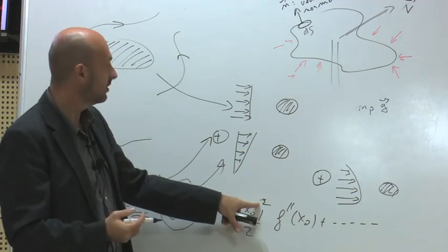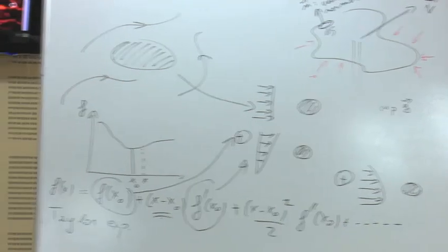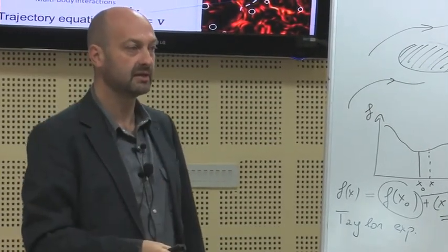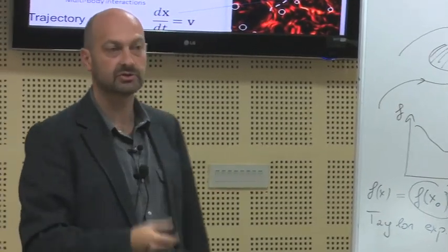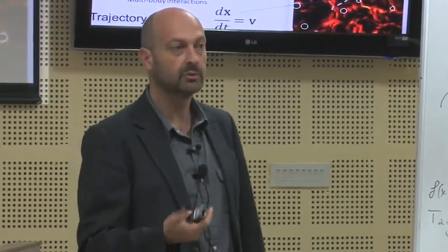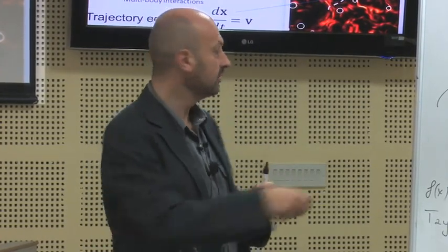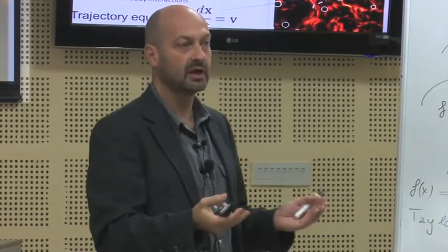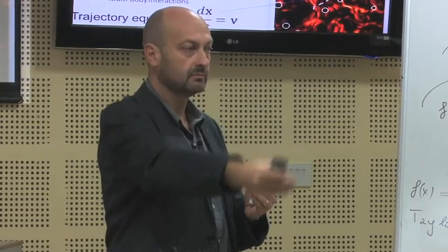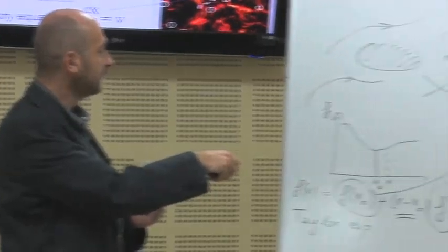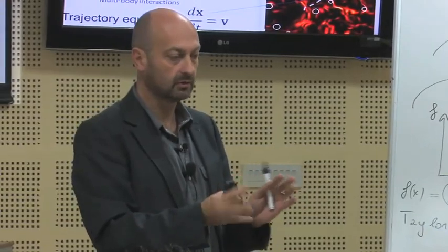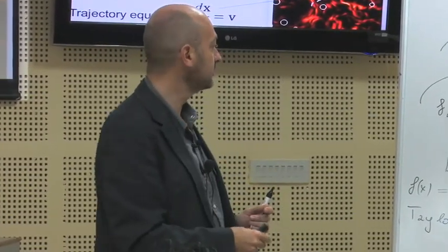So the idea of building this force balance as a decomposition, as a sum of elementary mechanisms, is to follow what is a Taylor expansion for a scalar function, but to adapt this approach to the force balance. When I have a particle within a complex flow, it is actually the sum of contributions. The first contribution is the drag, because when you have a particle in a constant flow, it will experience a drag, which has two origins, pressure and viscous stress.